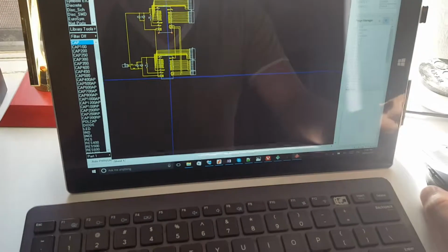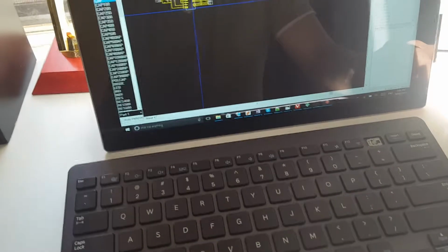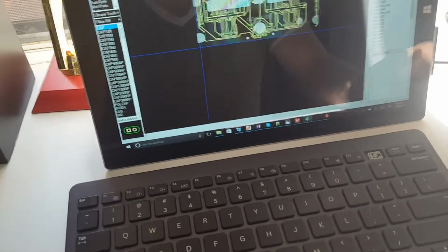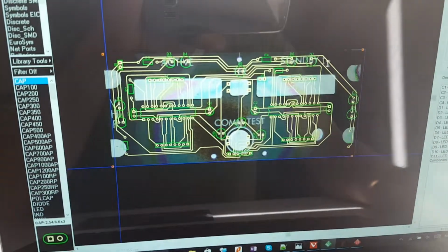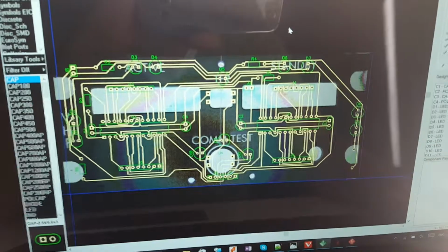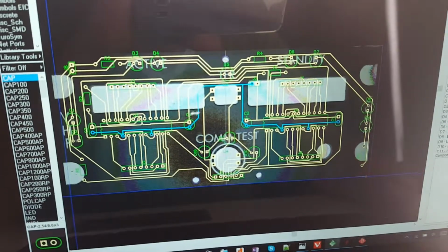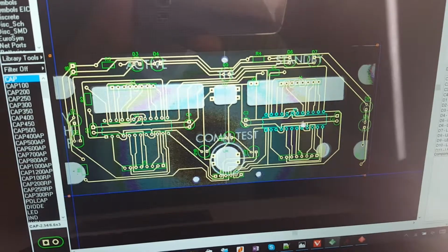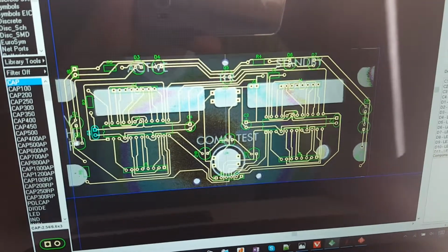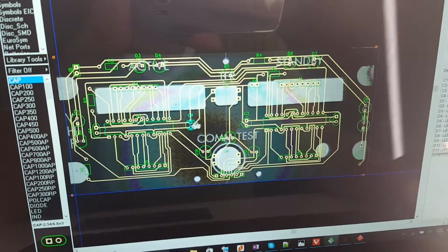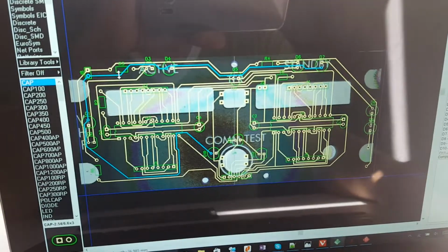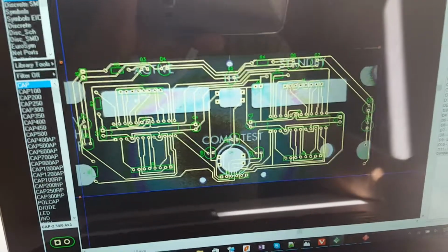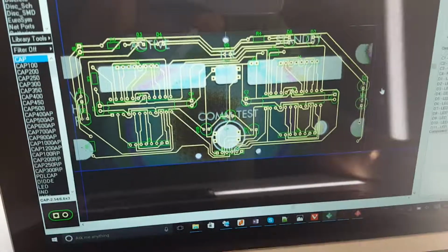Once you're done with the schematic, assuming it is correct, you transfer it into a PCB layout program. Here is where I use that photo I took earlier, and I trace out the PCB to the layout I want. Here are the 2 7-segment drivers, capacitors to control power ripple through them, resistors to control the current of the 7 segments, resistors to control the current of the backlight LEDs, and a few connectors here and there to connect it all to the Arduino board.